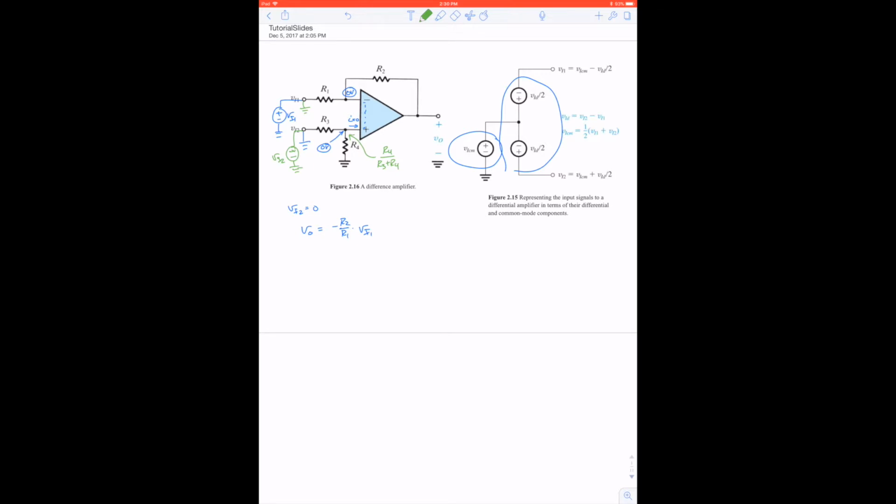So when Vn1 is equal to 0, Vout becomes 1 plus R2 over R1, that's the non-inverting configuration gain, times the potential at the positive pin. This was Vn2, so we can write that down: R4 over R3 plus R4 times Vn2.